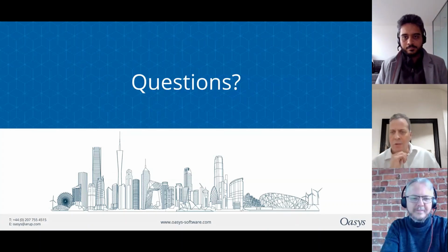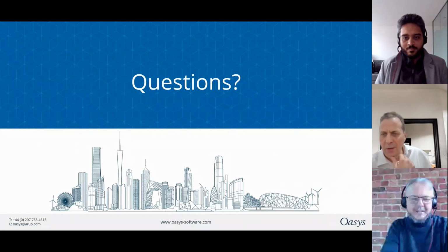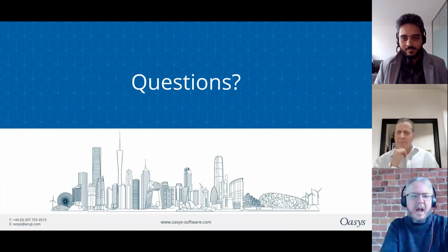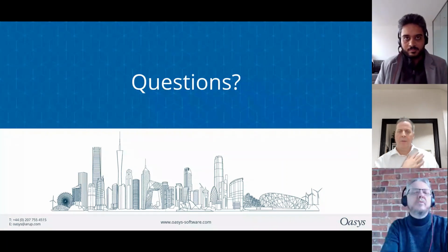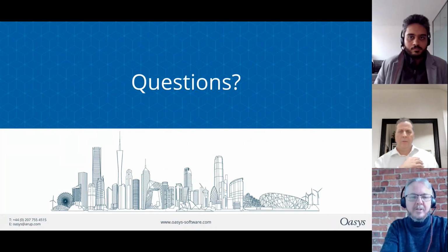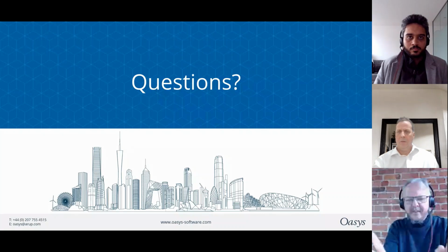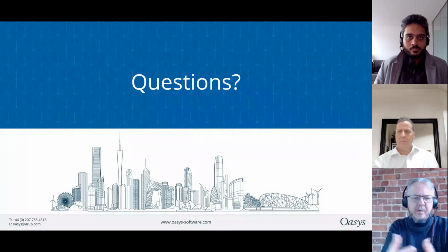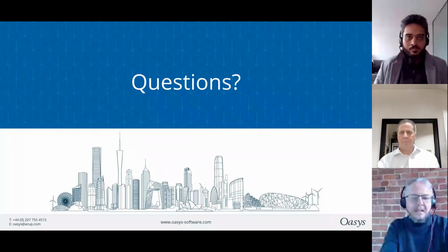Okay, we've had one last question that's just slipped in. Does GSA do pattern loading/checkerboard? Okay, so pattern loading, yeah. In terms of checkerboards, yeah, you can define checkerboard loading directly yourself. We do have a pattern load optimizer, which is actually much more comprehensive than checkerboard. Checkerboard is okay for a 1D approach. The load optimizer is good for full floors. And so yes, indeed, you can do that.